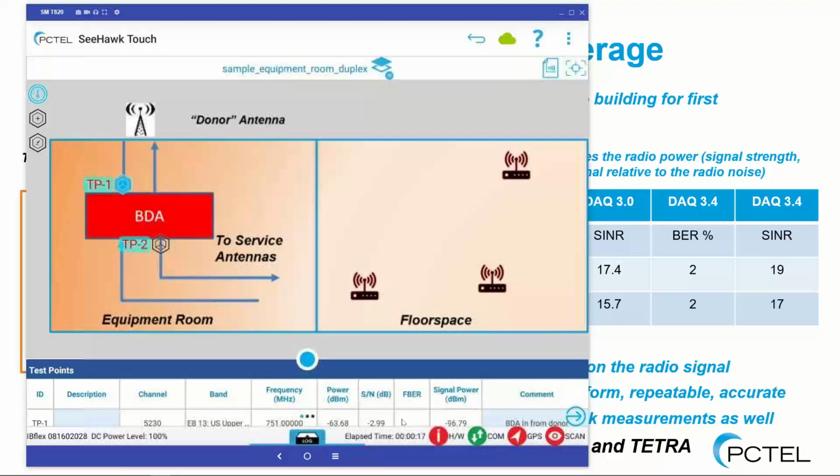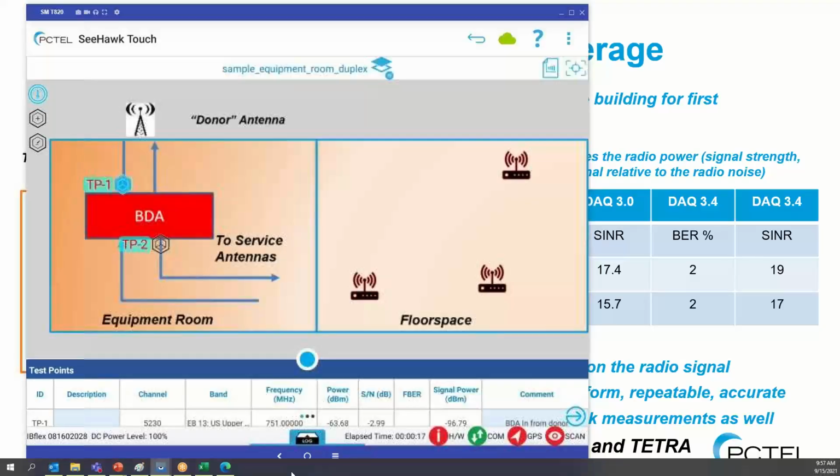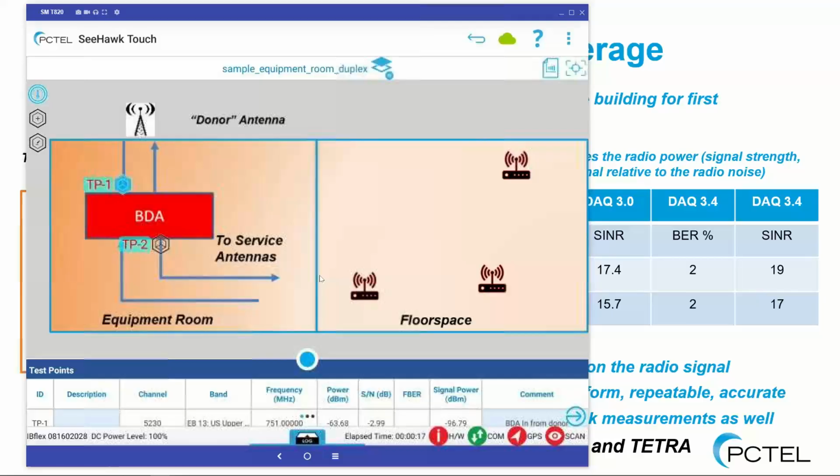Yeah, that's what I'm worried about. To be honest with you, at that point I would probably be back to either a spectrum analyzer or a watt meter. Or you can put an attenuator on. I don't worry about burning out the front end on it. Yeah.